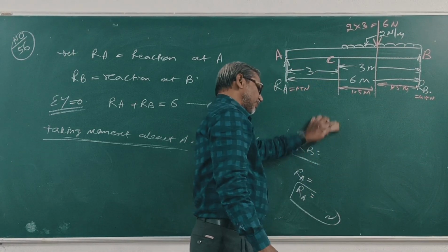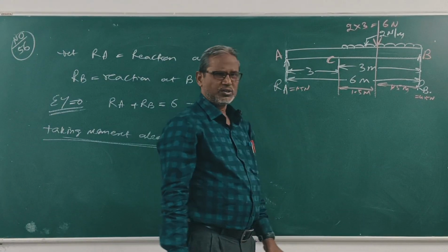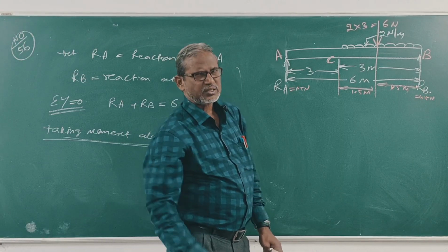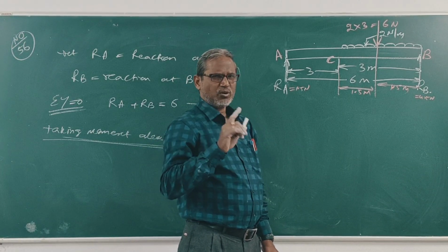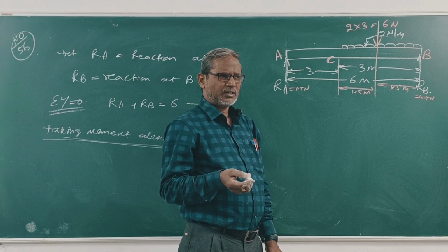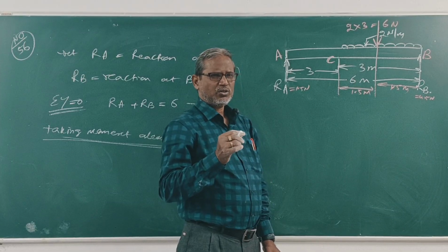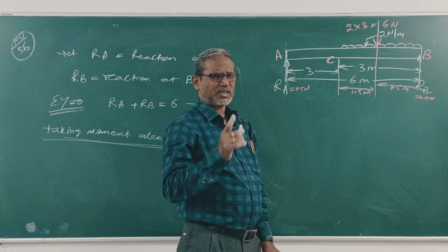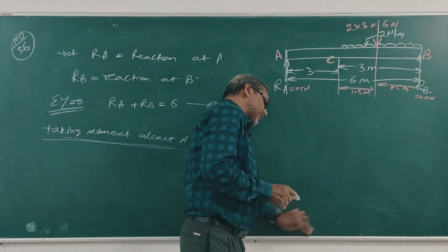Right? Now make the calculation for shear force. Then we will draw the shear force diagram. Then the calculation for bending moment. Then we will draw the bending moment diagram. In the bending moment diagram, we will find out the point where the shear force changes its sign. At that point, the bending moment is maximum. Clear?